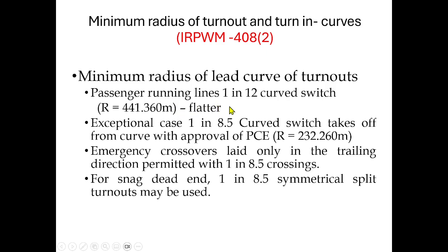Anyway, for recollection, if you want to lay points and crossing on a passenger running line, you must use only 1 in 12 and flatter. You should not go for the 1 in 8.5. This is as per the manual provision 402.